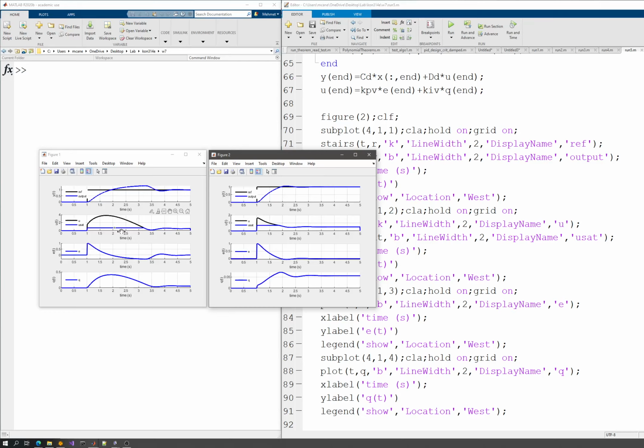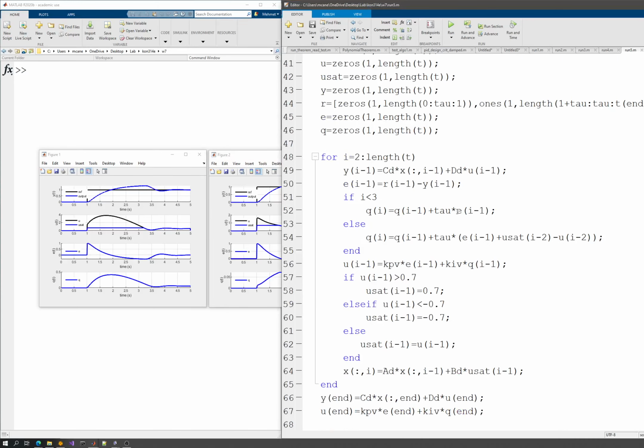So basically what you have to do is implement an anti-windup into your controller. In most of the modern PLCs and in most of the control cards, there are anti-windup structures embedded into them. So it's very basic, and it is very important to mention this here. Now the other strategy is to just switch off the integrator. So how can I do that? Let's say if I is less than this, it is that.